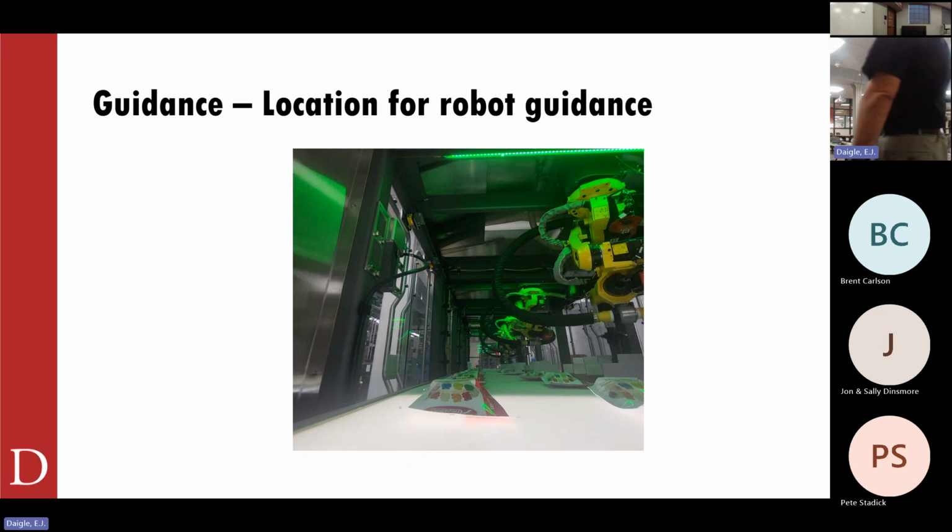If I was at greater than 45 on bright field and lower than 45 on dark field, what that means is more or less of the light is going to reflect back to the camera. So if I'm shining light at this part and I'm either high on the part or low on the part, I'm going to reflect more light away from the camera or more light towards the camera, depending on the angle of my lighting coming in at it. Make sense? Yeah. All right.